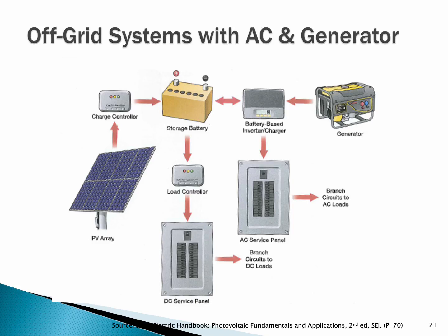So in an off-grid system, that inverter is going to be able to operate independent of the utility, because there is no utility, and operate off a low voltage battery pack. But then it also has to be able to charge. So this is an inverter charger. So I hook the generator up to the inverter and run that for a couple hours, and it'll top off the batteries.